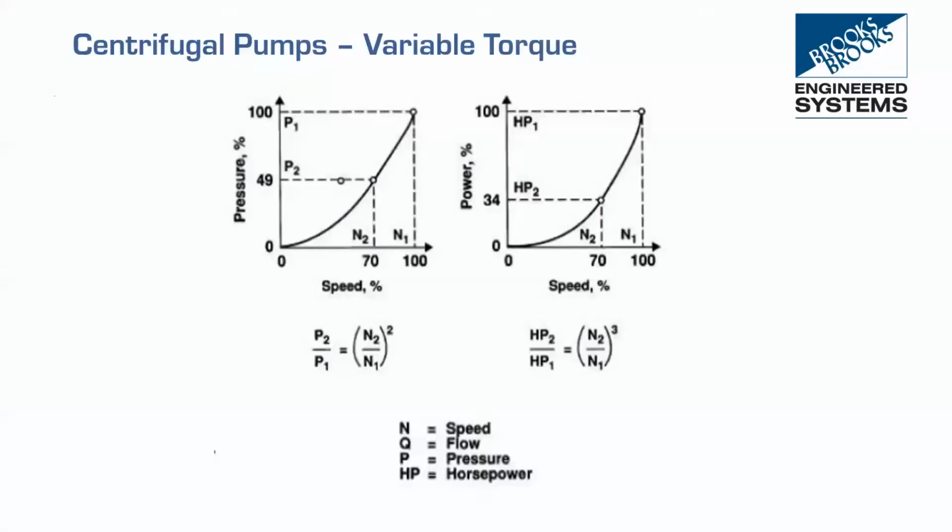Yep, that's correct. And centrifugal pumps follow the affinity laws. As we speed up that impeller, the pressure developed by the impeller and also the torque on the shaft are going to increase with the square of the speed. The power required to turn the shaft is going to increase with the cube of the speed. So we can see on these graphs that when we're operating close to zero, both the torque and the power required to turn that pump shaft are pretty minimal.